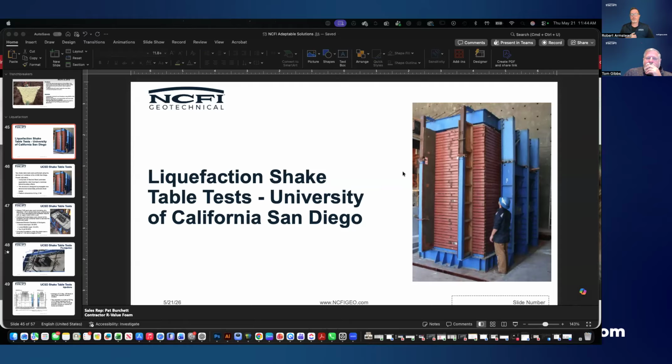It's not going to stop the expansion from occurring, but at enough saturation, it might prevent some of the water absorption. We typically advise and utilize it depending on the condition of the soil from a saturation standpoint. If it's extremely dry, it can permeate and fracture all the various elements of the expansive clays, especially as it's dried and a little bit brittle.